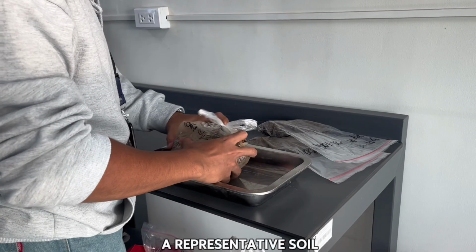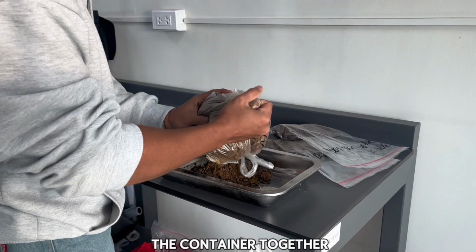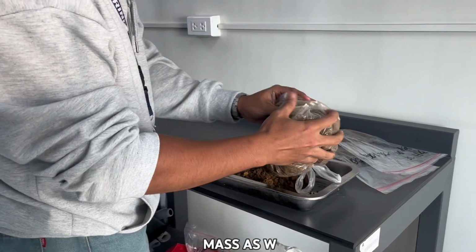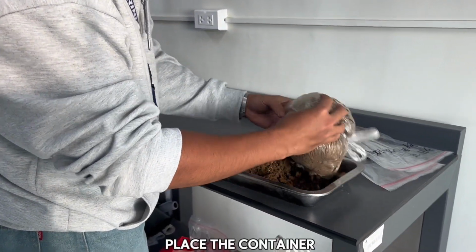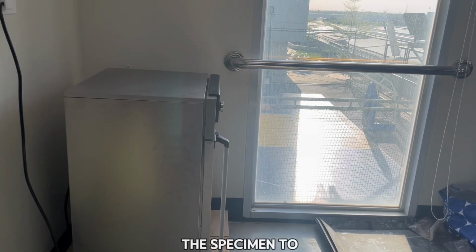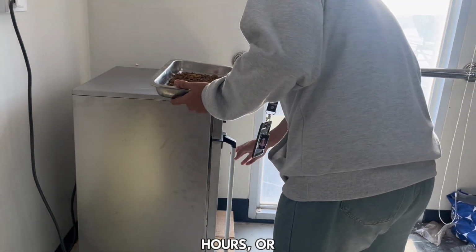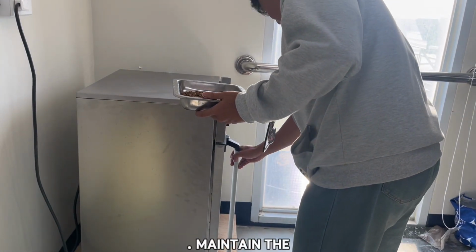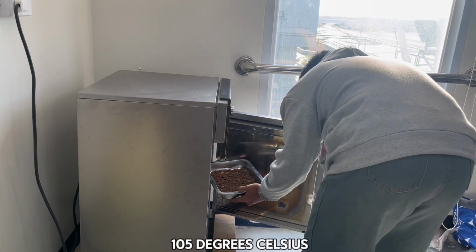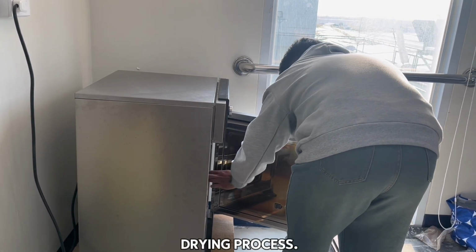Next, place a representative soil sample into the container. Weigh the container together with the moist soil specimen and record the combined mass as W2. After weighing, place the container with the soil sample inside the oven. Allow the specimen to dry for approximately 16 to 24 hours, or until it reaches constant weight. Maintain the oven temperature between 105 degrees Celsius and 115 degrees Celsius throughout the drying process.